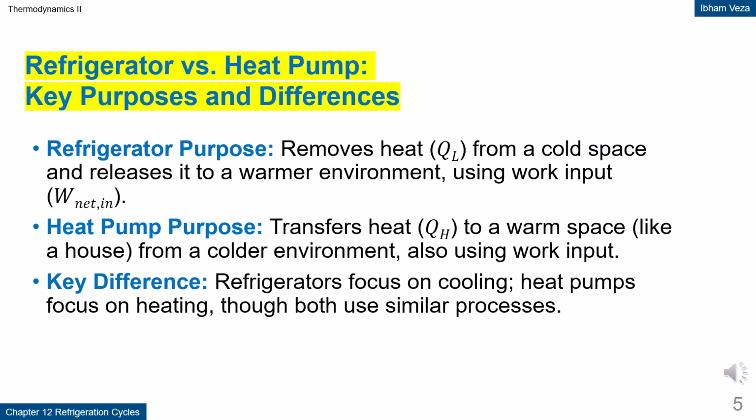Refrigerator versus heat pump. A refrigerator is defined as a device that removes heat, QL, from a low-temperature space and rejects it to a warmer environment. A heat pump uses the same principle but focuses on the heat, QH, delivered to the warm space. Both require work input, Wnet, to operate. From an energy perspective, the systems are identical. The only difference is the definition of the desired effect.